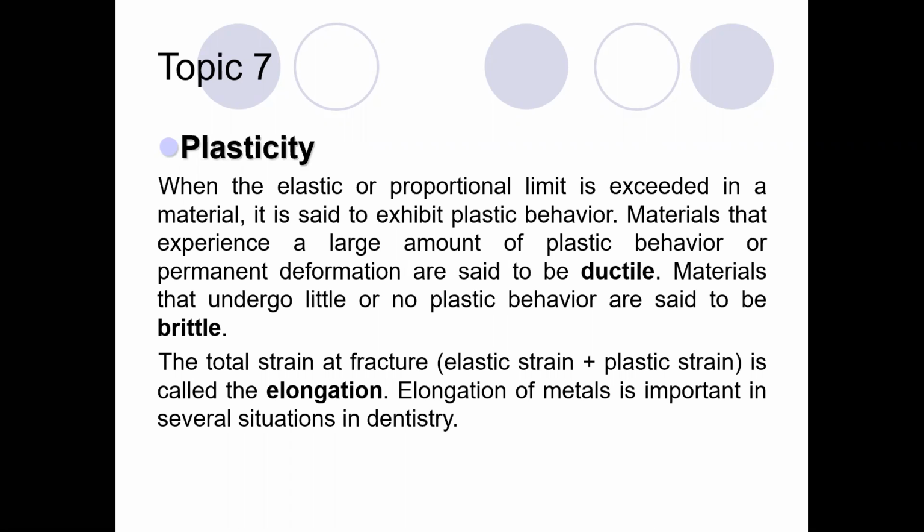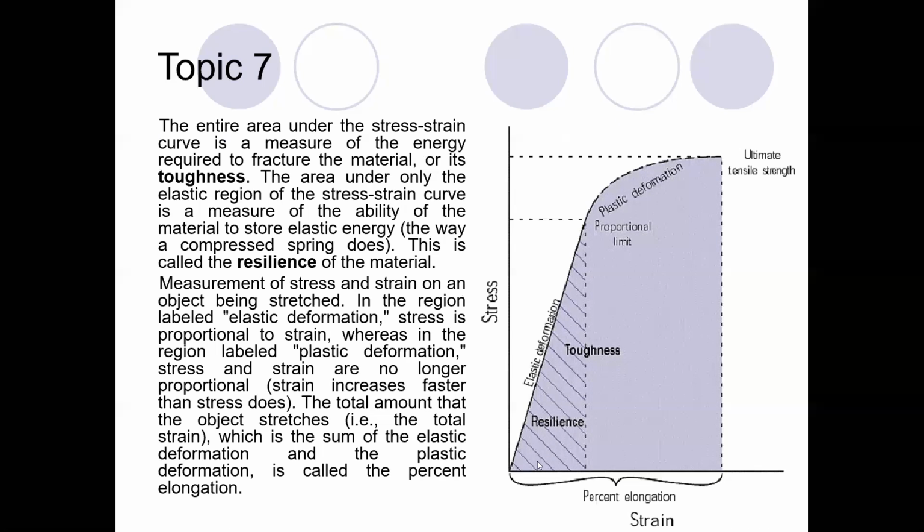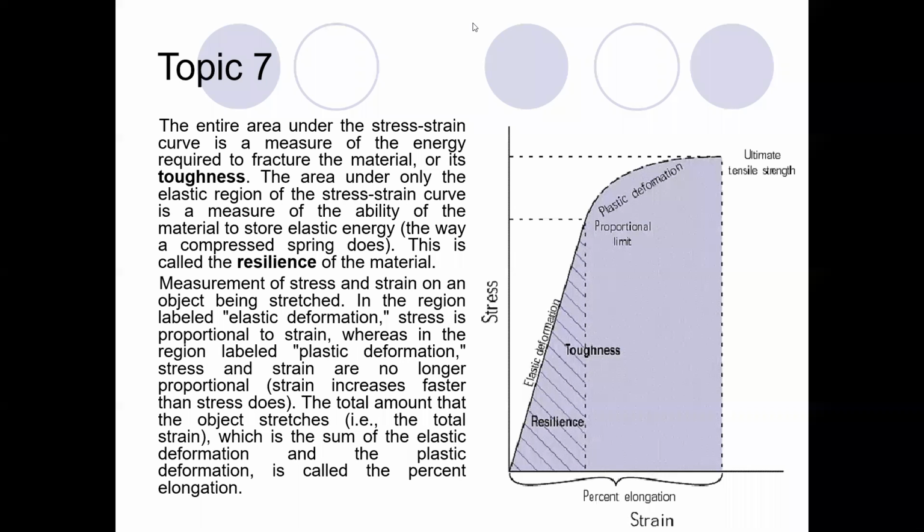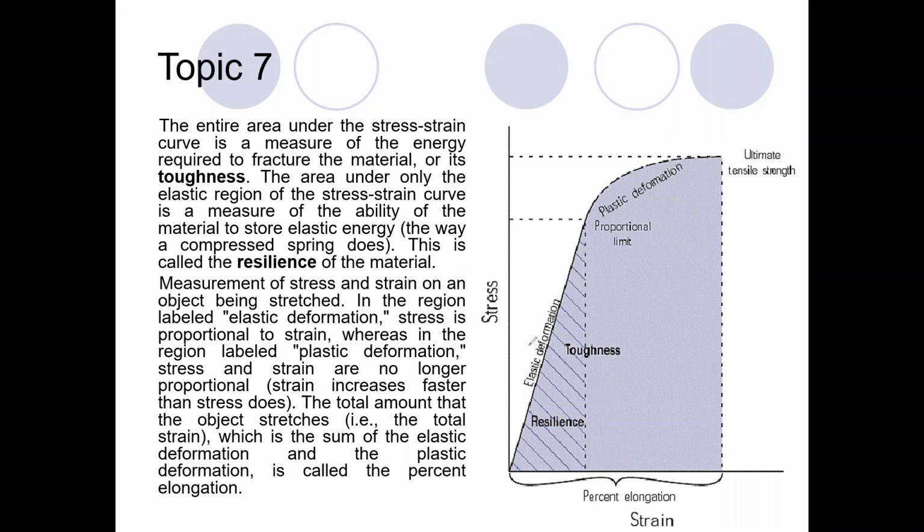And we can also measure from that graph different things that characterize the energy. All the energy required to fracture the material is that total area under the curve. Here, I crossed it. It is toughness, the energy required to destroy the material.